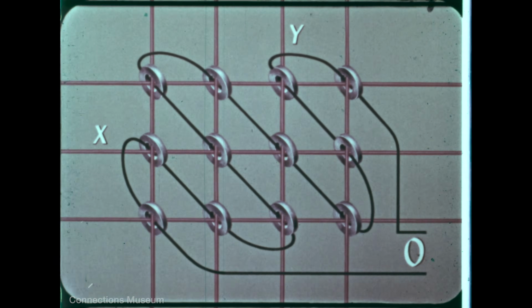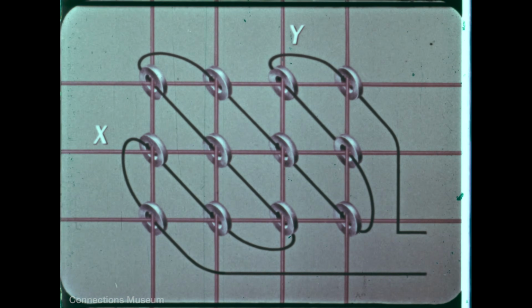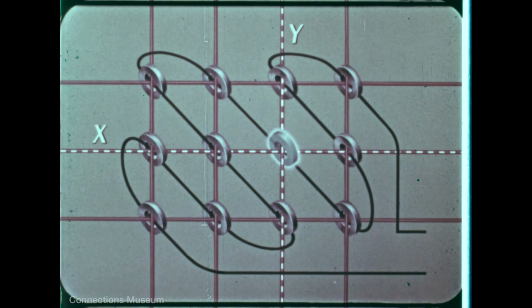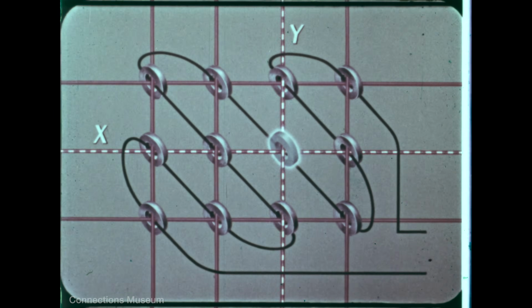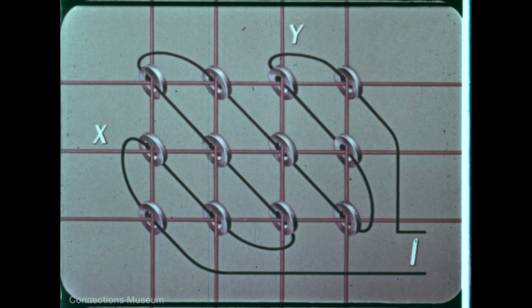It's apparent that the read pulse will erase the information held by a core, so a regenerating circuit automatically rewrites a bit after it has been read. A bit can be read out and rewritten in about 10 millionths of a second.